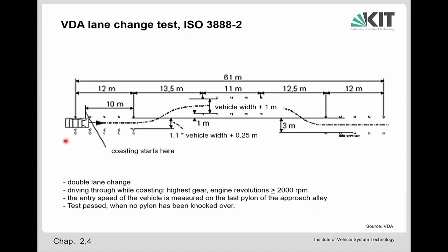So we have like a force peak, and this creates a super high friction, a super high braking or side force which can be transmitted between the tire and the road, so that it is more or less that the wheel is welded to the ground in that situation.